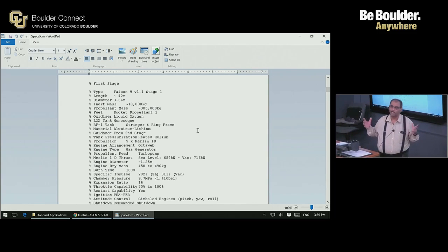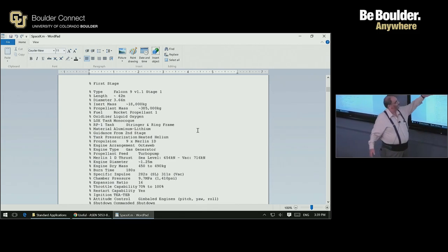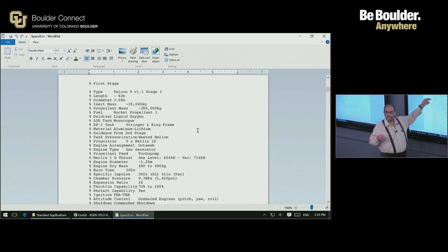So essentially think of it as useless mass. It would be nice to build a rocket vehicle with zero inert mass, but it's not possible, hypothetically. So you have to have some mass. But the whole idea of design is to minimize that as much as possible. It tries to squeeze out as much mass as possible out of the inert mass, yet retain reliability. Okay? Not at the cost of reliability.